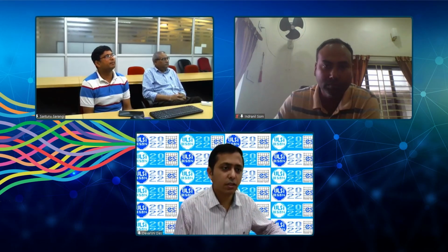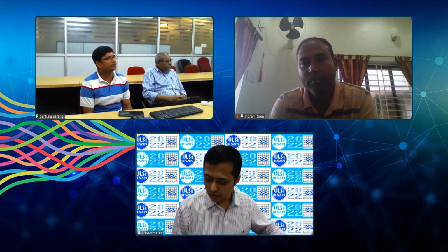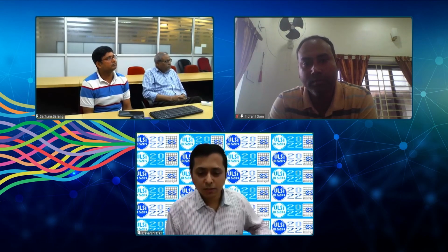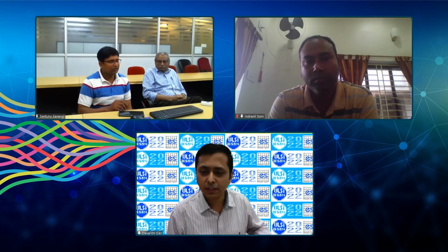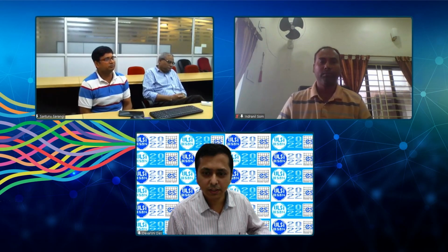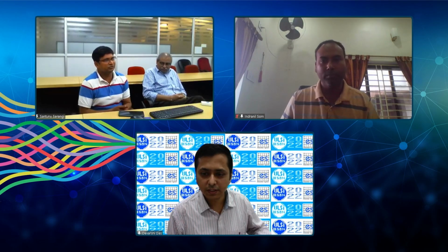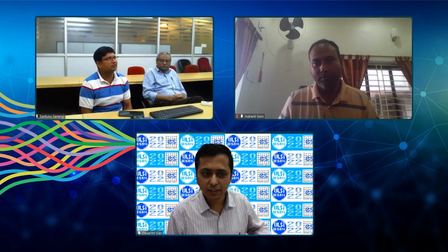Thanks, Indranil, for the clarifications. I have one question. The jitter to voltage converter circuit that you have shown has one capacitor, right? There is no discharge mechanism shown in it. So I was just wondering, how do you discharge that capacitor? Maybe in that figure, one transistor is there. Sometimes it will reset to discharge all this, but maybe I have not drawn that transistor, but there is a path.